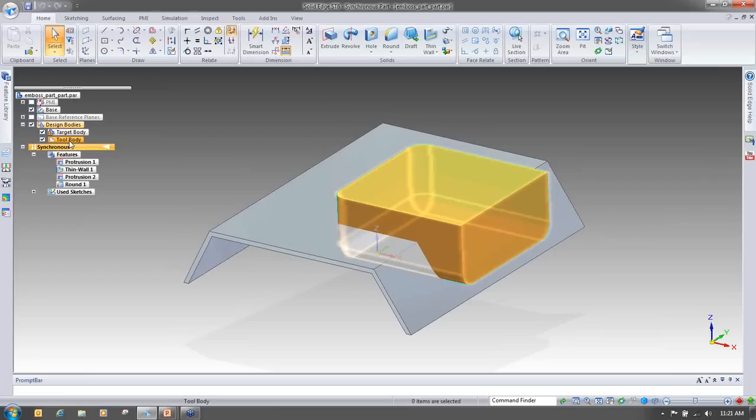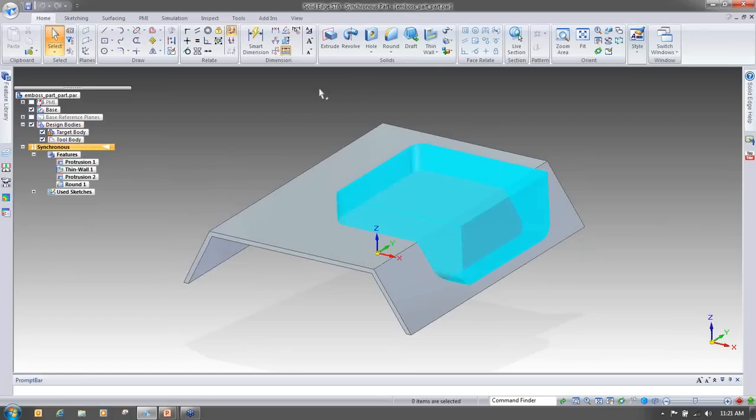If you think about it this way, we could design our punch, and then it would be just as if we formed that punch into the material and it took the shape of that punch. Pretty cool stuff. We can mimic the actual design process and manufacturing process, if you will, just by setting it up so that we have a tool body and then a target body. Now, the thing I need to point out here is that I created these through the multi-body functionality.